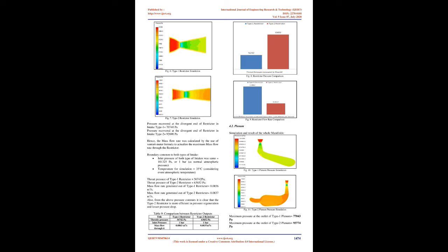V equals pressure wave speed equals 1152 feet/s. D equals runner diameter equals 44 mm equals 1.73228 inch. RPM equals rotations per minute equals 5000 RPM. RV equals reflective value. L equals length of runner. So, from this the length comes out to be equal to